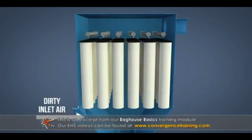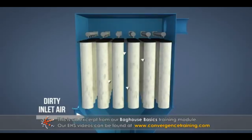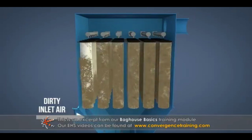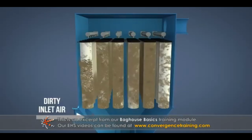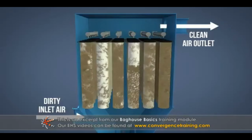One, the dust-laden or particle-laden air or gas stream enters the baghouse, travels along the surfaces of multiple fabric tubes, and then passes outward or inward through the fabric. Two, the larger particles fall down into a hopper, while the smaller particles accumulate on the fabric surfaces. Three, a cleaning mechanism occasionally removes the particles from the fabric tubes, and they fall down into the hopper from which they are discharged. Four, the clean air or gas stream exits from the top of the baghouse.